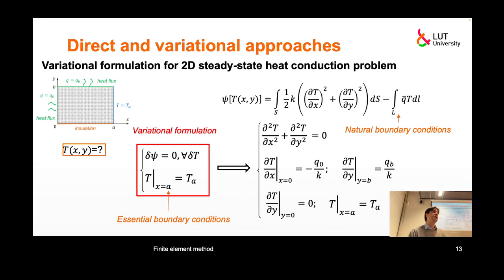what is the default boundary condition. If I don't say anything explicitly in a commercial code, for instance, about boundary condition, what will the code assume? Well, from this formulation you can also already see that it will assume something 0, but what 0? Temperature 0 or heat flux? Okay, since there is this variational principle inside this functional, it will form this vector, and if I am not prescribing anything, it forms the 0 values here.